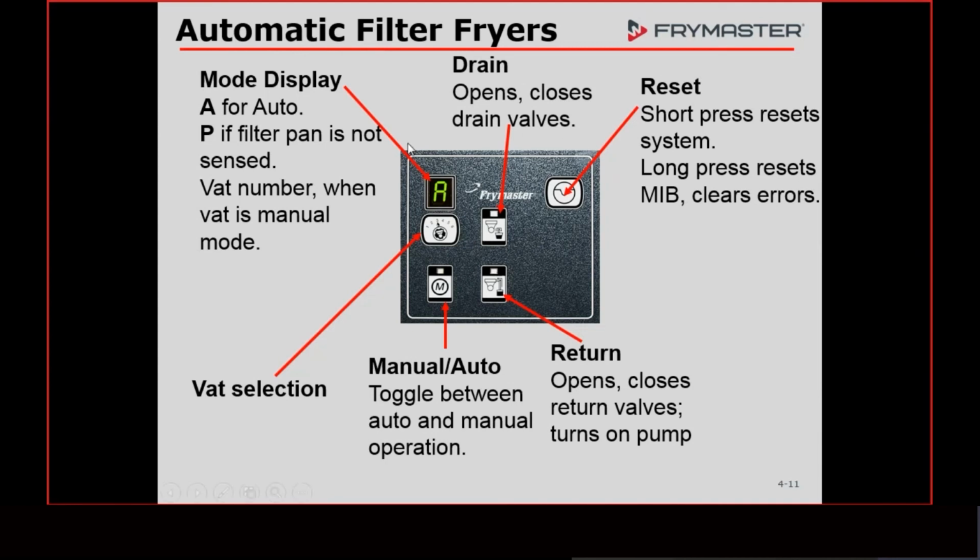Sometimes if you get an AIF error on a fryer, always disconnect the actuators too, because sometimes a bad component on a board will weigh it down. That's kind of more what we talked about yesterday. But anyway, those actuators sometimes go bad. They work hard. If they go bad and they're causing a short or something like that, it's going to show up either here or it's going to give an error on that AIF board. It could just be an actuator. But that's how you can troubleshoot an actuator.